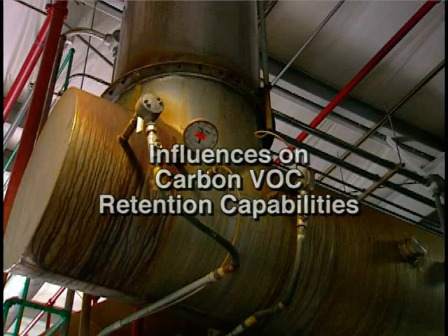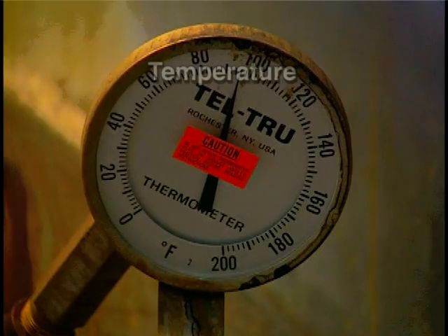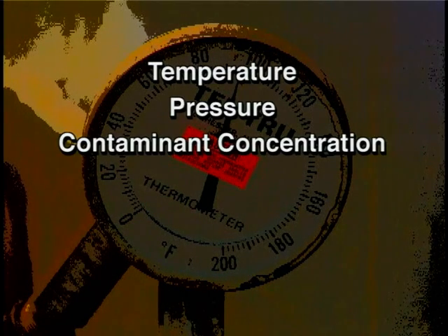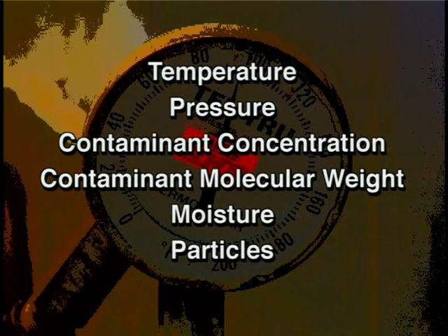The ability of activated carbon to retain organic contaminants is influenced by a number of parameters, including temperature, pressure, contaminant concentration, contaminant molecular weight, and the presence of moisture and particles in the gas stream.